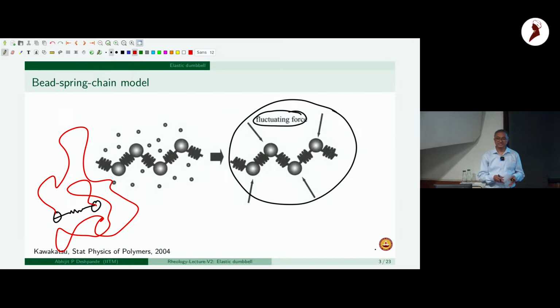And two essential mechanisms which this microscopic mechanical analog captures: the polymer chain has an entropic elasticity, in the sense that the conformational degrees of freedom are high when the two ends are closer together, but if we apply shear, then the two ends tend to move apart, and therefore the conformational degrees of freedom reduce and the entropy of the chain reduces.